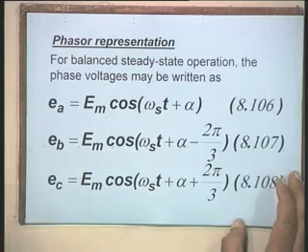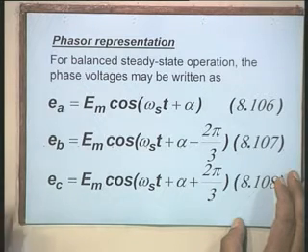But here also, although these quantities are constant in magnitude, because of certain trigonometrical relationships which exist, we will be in a position to represent these D and Q axis voltages and currents as phasors, but with a clear understanding in our mind that D and Q axis quantities are scalars.